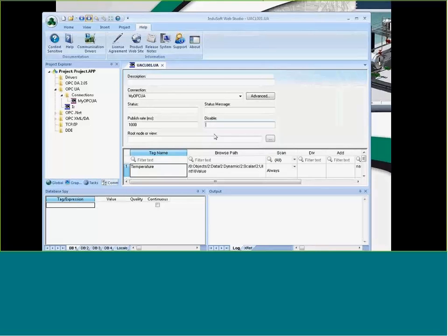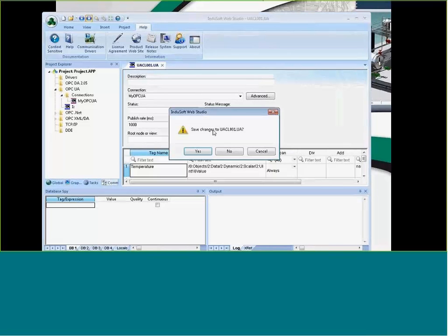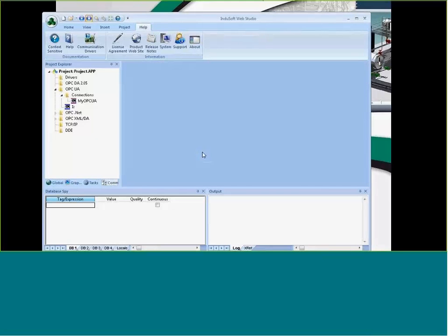In this case, while I'm testing, let's say, and I don't have the PLC, which is what the question was, I'm just going to put a 1 in there to disable this whole worksheet. I can fill out the whole worksheet and then just disable it, and it'll just sit there waiting until I turn that back on when I have the PLC in hand. Now that that's disabled, like I just showed you in that help system, I won't be communicating to the OPC connection, if you will.